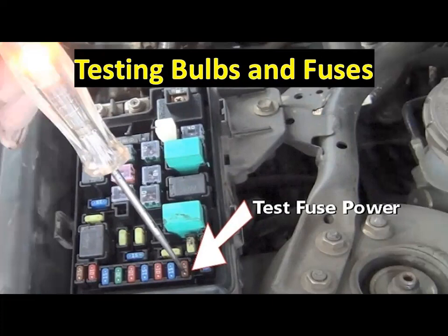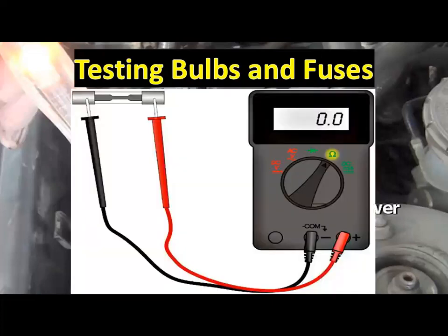You test the two metal points with a circuit tester, and the circuit tester lights will turn on if the fuse is working okay. With an ohmmeter, a 0 ohm reading indicates a satisfactory fuse, and a high or infinite reading indicates an open fuse.